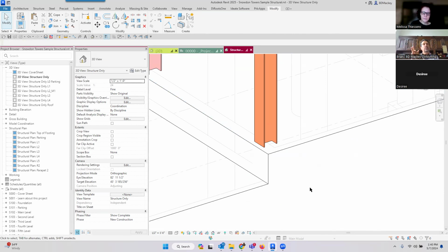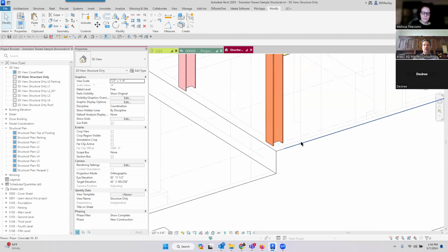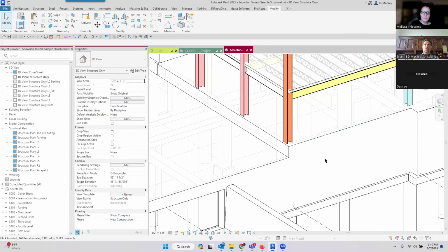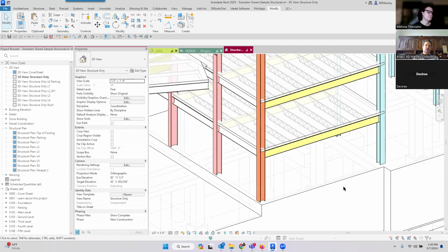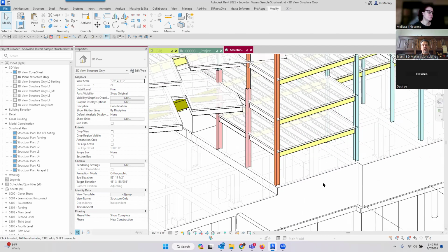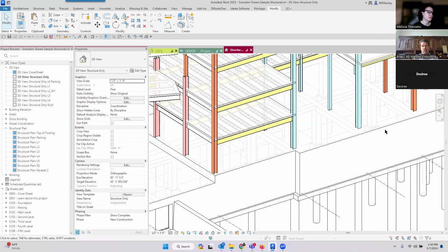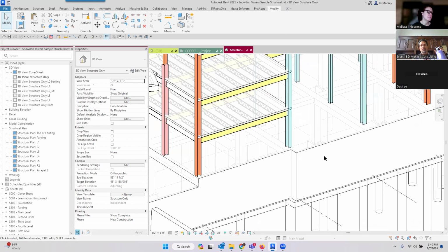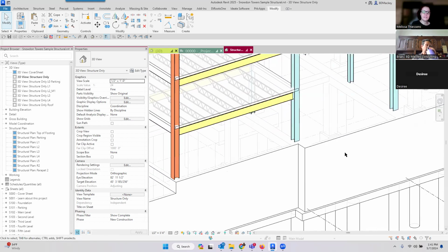I've not ever seen those print, but I do know exactly what you're talking about. I do the same thing, I just model the sheathing as its own floor. And then I always see the walls underneath that sheathing where they come up to the sheathing. It doesn't even have anything to do with the join. It's just the fact that I've got a very thin surface. Revit's attempting to show that through the surface, and you'll see those ghosted lines. I've never had them print on me, but it is kind of an annoyance because you're zooming around the file and you see all these little ghosted lines. Like, oh, I don't want to see those. But yeah, that's just kind of a surface battling happening in your graphics display.